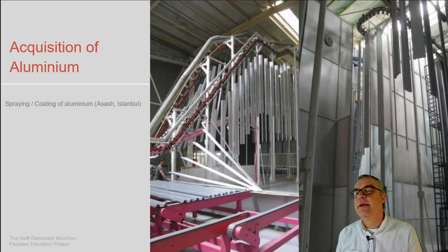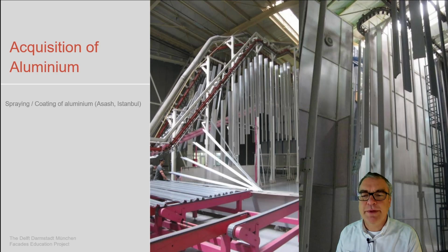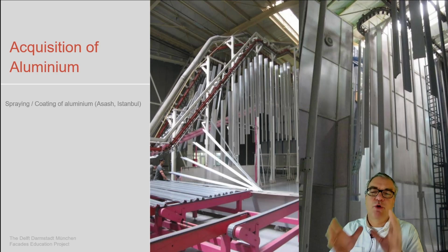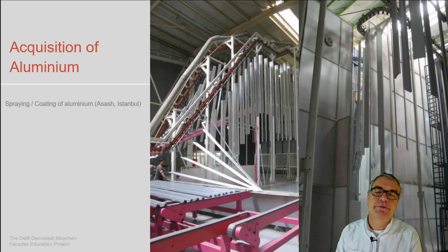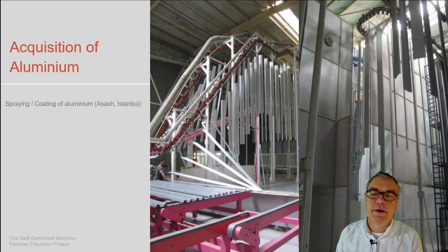The next level of dealing with the aluminium is the corrosion process. The aluminium surface corrodes very fast. It doesn't continue deeper, which means that we either keep the aluminium as a raw material with the corroded surface, which is this nice shiny, silver aluminium-like surface, which is one way to use it. The next way is coating it with a paint.